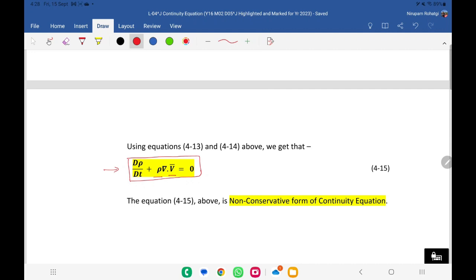In one case, the parameters are inside the derivative, in another case, parameters are outside. Now, these two are exactly the same when we talk in terms of derivatives. No doubt. The moment we discretize it, though, the discretized equation is not the same as the original equation. Remember, when I talked about the errors in CFD, I told you there is something called truncation error.